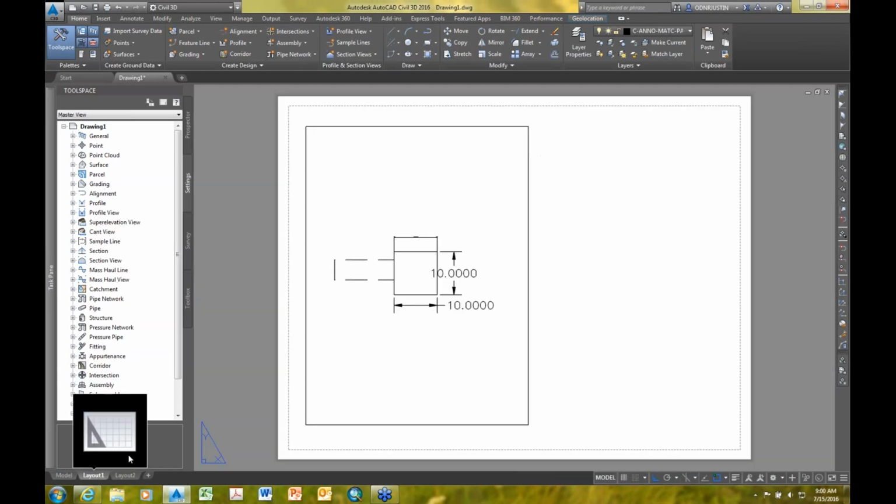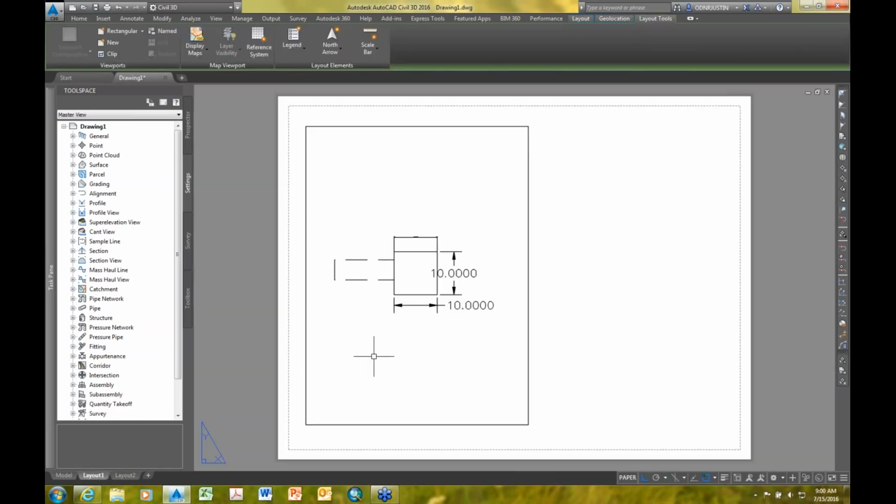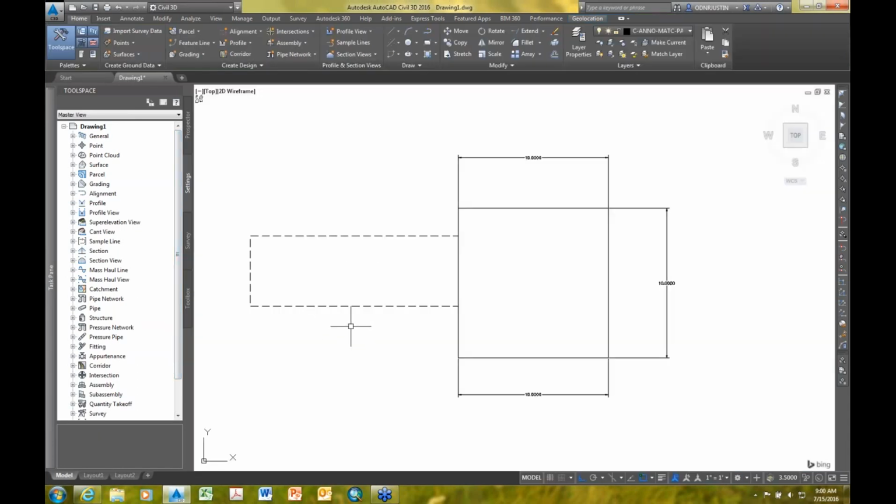Okay, and if I go back and look at this in my paper drawing in my viewport, oh Nelly, the dashed line doesn't quite look like what it was supposed to. And again, that's because I'm drawing it at a certain scale, and then my viewport is scaling everything up. And I've set the drawing to do the hatching according to whatever my model space is.